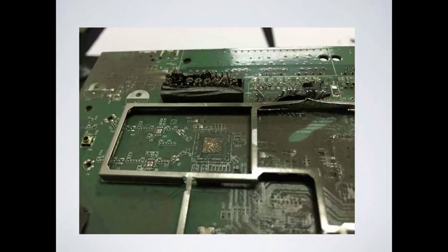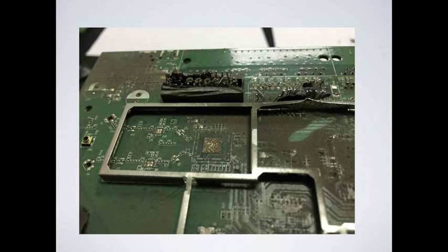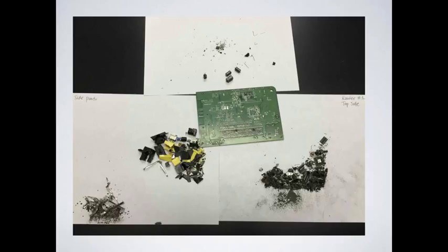This one was kind of hard to take off, the heat sink here. There are like four little sections where it's going through hole. You kind of have to heat up one side. What I found really nice is that if you just take off the solder and then pull up, it works. Then heat the other side and kind of peel it back, and it comes off. And then I got everything off. It was all fine and dandy.